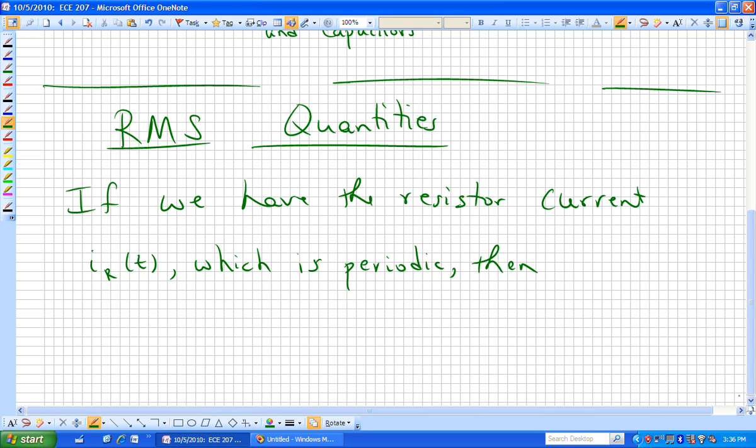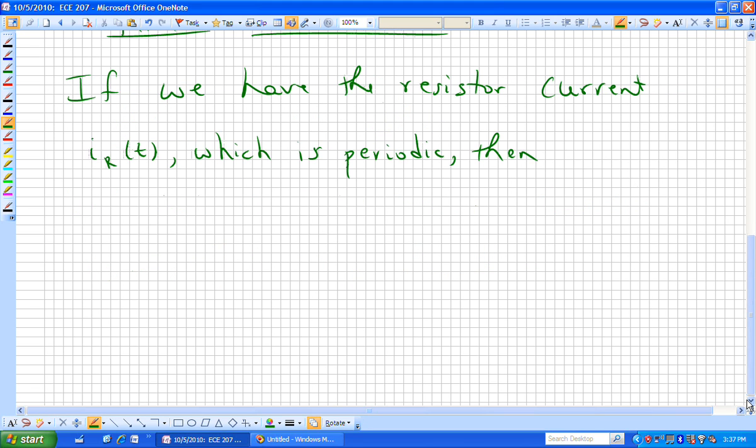And when we do that, we can immediately go from the time domain waveform with a magnitude, a frequency, and an angle to its phasor representation, because we know the relationship between the time domain signal's amplitude and its RMS amplitude that we will use in the phasor notation. But if we just have a resistor that's being excited or driven by a sinusoidal waveform, then we could find the RMS current through that resistor by doing what it says, I sub RMS.